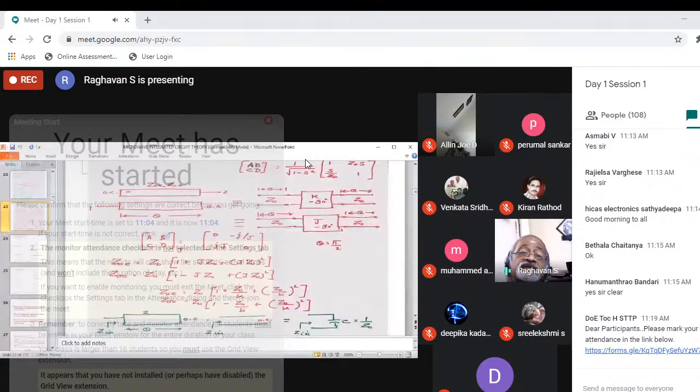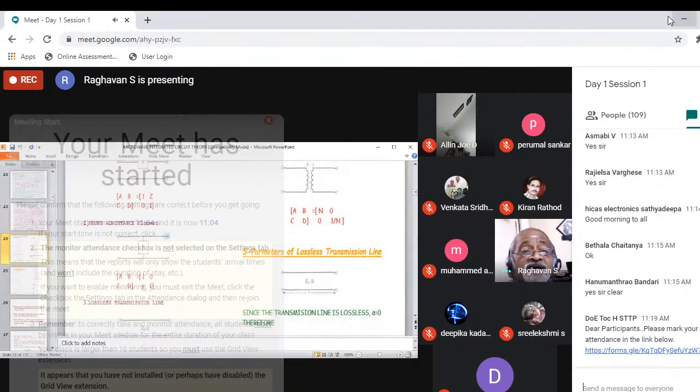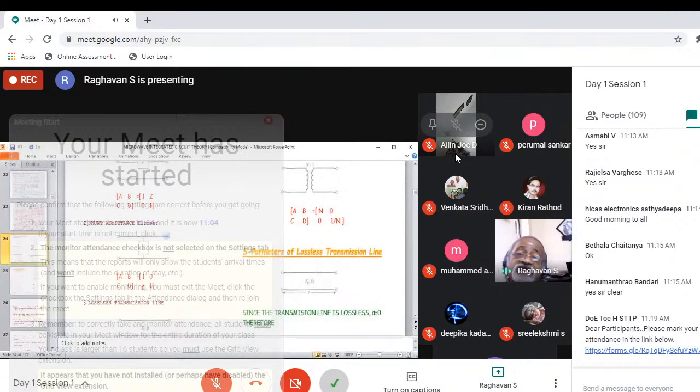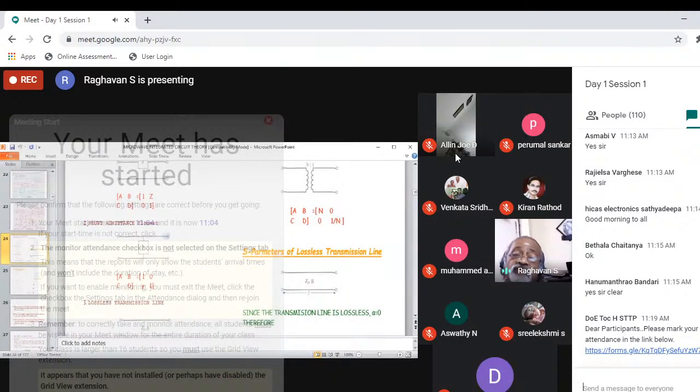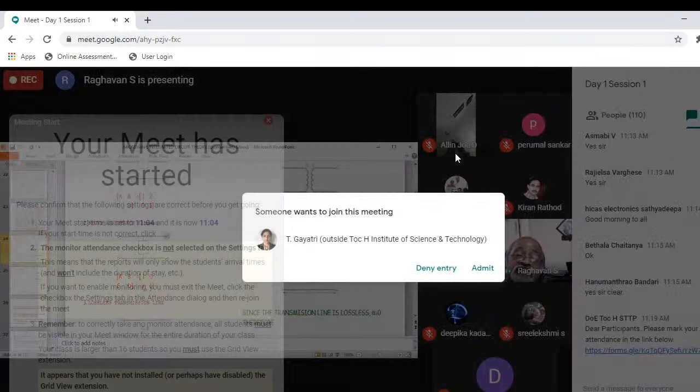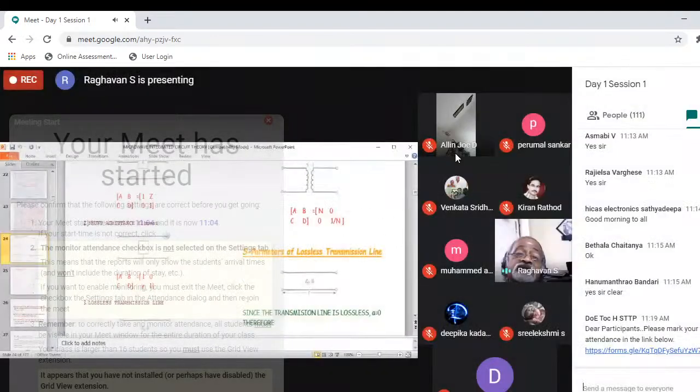So this slide is the summary for the bandpass filter, and also for the open circuit, short circuit, ZOC and ZSC, and ABCD parameter that you can easily derive also. Expressing V1, V2 in terms of I1 and expressing V1, I1 in terms of V2 and minus I2. And just like that, I told you L and C are the two things throughout the world. There are only two types of connections, series connection and parallel connection. So ABCD is 1 Z 0 1, and for admittance it is 1 0 Y 1.